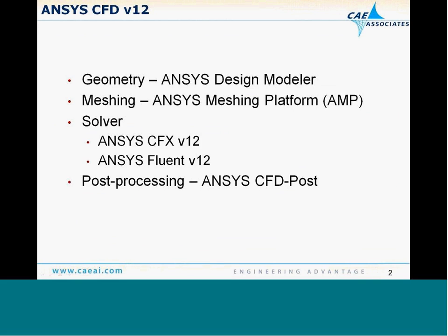So that's the flow chart in the ANSYS CFD 12 release, from start to finish to complete a CFD analysis. Next slide, and just outline these components: Design Modeler, meshing, and solvers. When we come to the solver part, you have the choice of either going with the CFX route or the Fluent route in 12. And once it's converged, of course, you take that into post-processing.